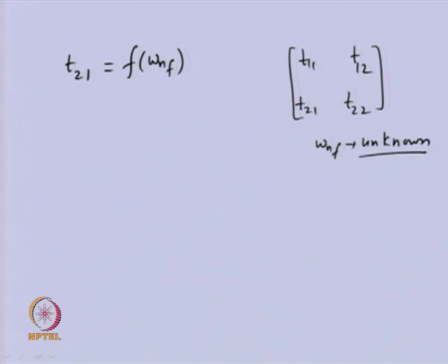So unless we know this, numerically we cannot multiply the point matrix and field matrix. So for that purpose, when we solve the natural frequency using a numerical technique, we assume some initial guess of the natural frequency, let us say a very small value, 0.01 radians per second. Once we assume this, then we can see whether this particular function, the frequency equation, is satisfying this particular function, because this is the initial guess.